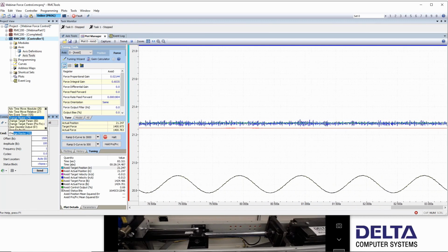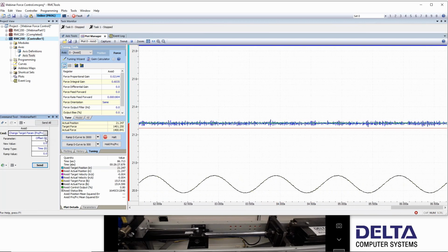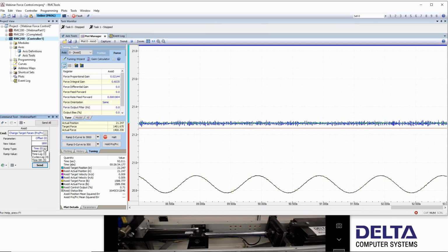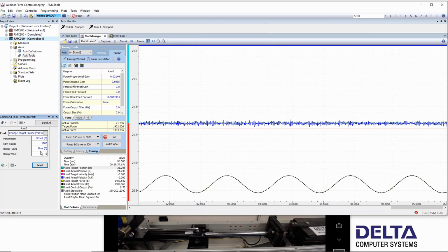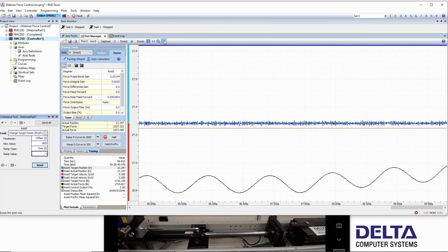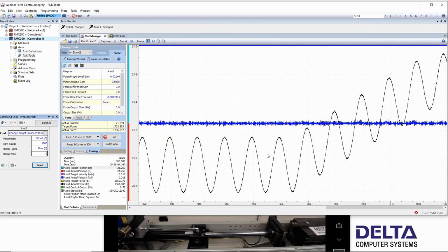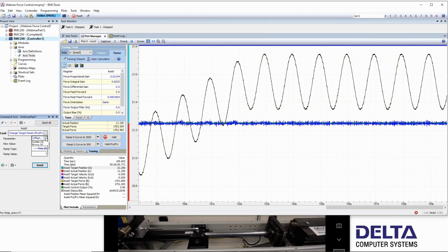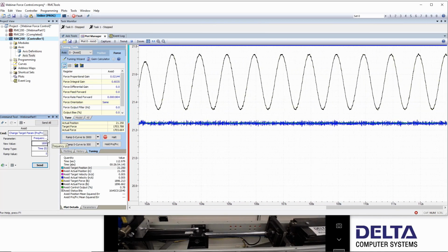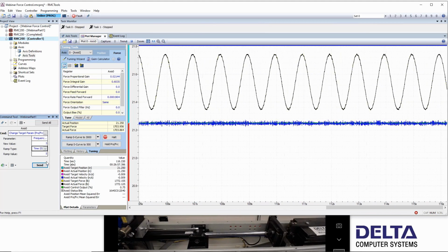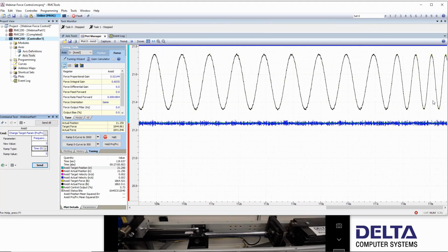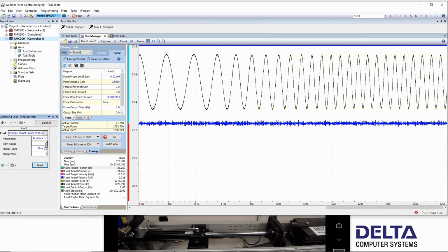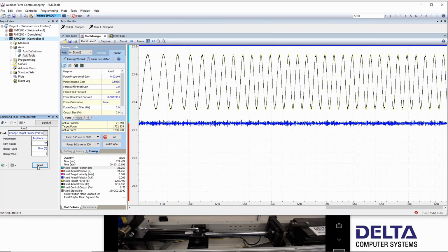We have this cool command called change target parameter, and we can change the offset. Let's change that to 1800, and we can choose over time or cycles or whatever. We'll choose over time, maybe 5 seconds. So now we should see that the offset is changing. I zoomed out a little bit here. The sine wave moves up, and we can change the frequency. Let's change the frequency to maybe 3 hertz, and we'll do that over 5 seconds as well. So now we see the sine wave over here is speeding up. And we can reduce the amplitude as well. Let's reduce that to 20. We'll change that over 5 seconds as well.